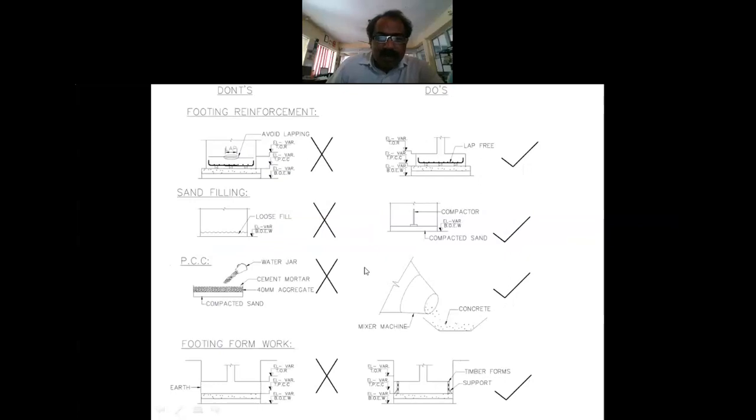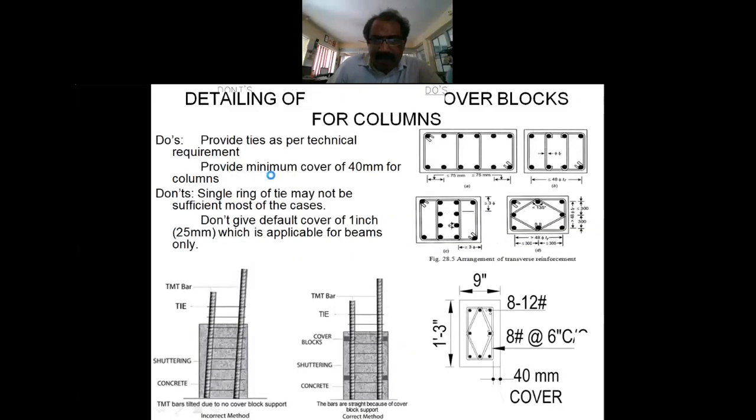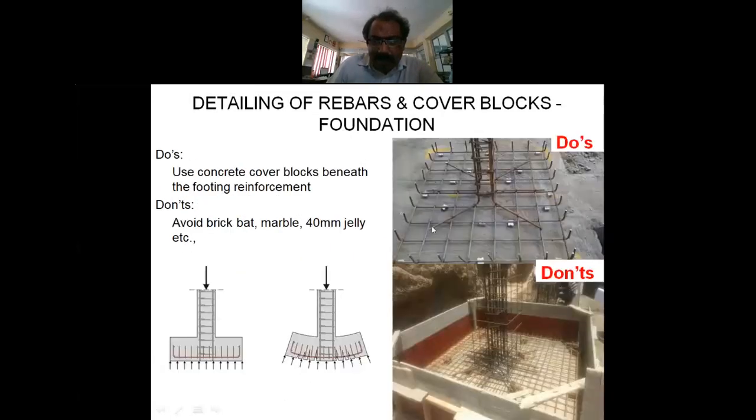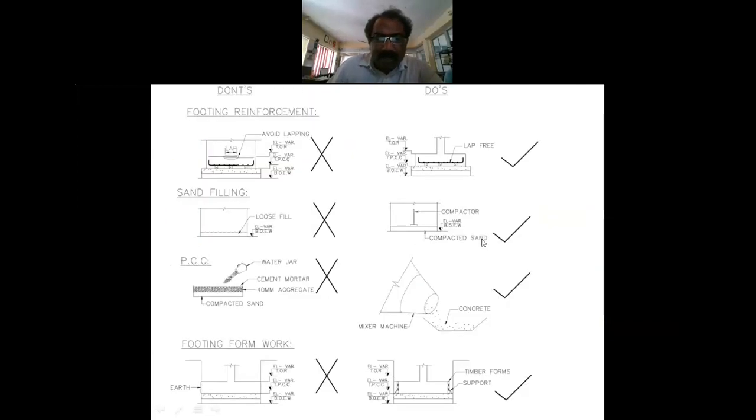And in footing reinforcements, don't do lappings. Don't make laps. Put straight bars as far as possible. Put lap-free straight bars.